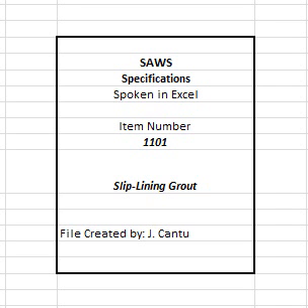a factor. D. Pumping. 1. Design grout mix to be pumped through a 2-inch diameter hose for a distance of 1,000 feet, with a maximum allowable pressure at point of placement of 5 psi. The cast density shall be 55 pcf, plus or minus 5 pcf.